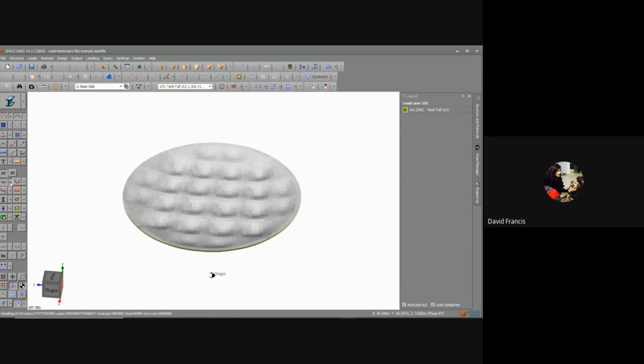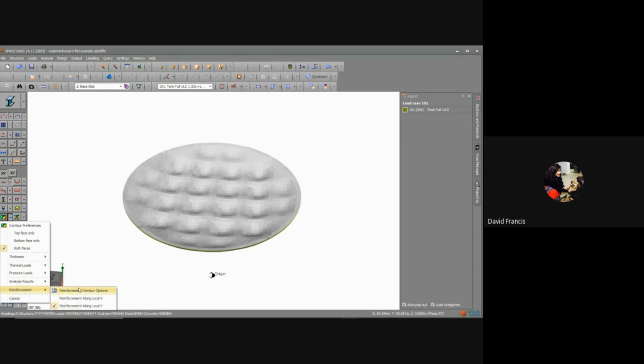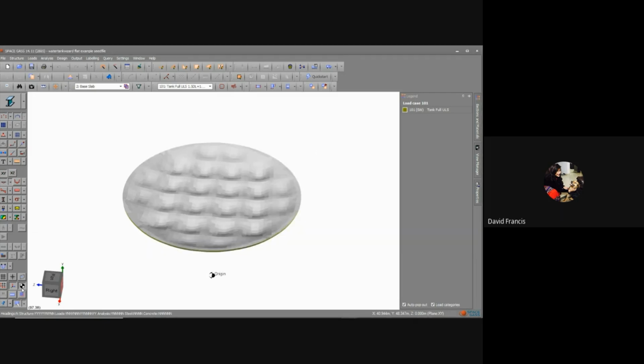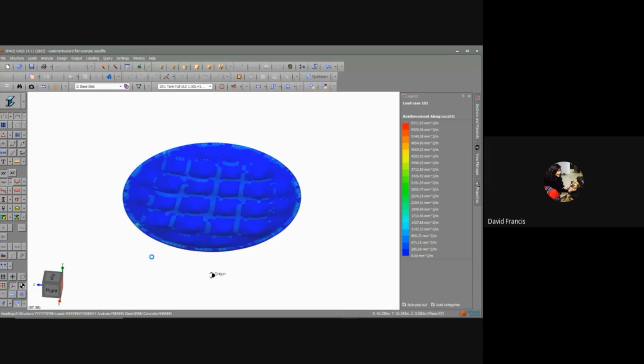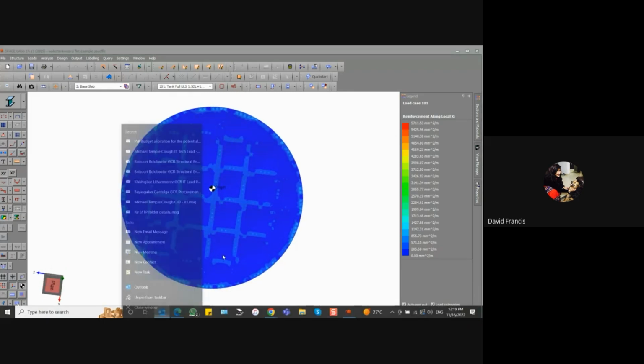And at this point now, I can start looking not just at deflections, but at the analysis results. I can also go and look at reinforcing, and there are contour options. And you'll see that currently it's configured for IS 456 2000. And there are some controls in terms of what you can do for the output. The other design codes, of course, are the Australian design codes. So going back to my reinforcement, I can show the reinforcement in different levels, both on the deflected shape or not.